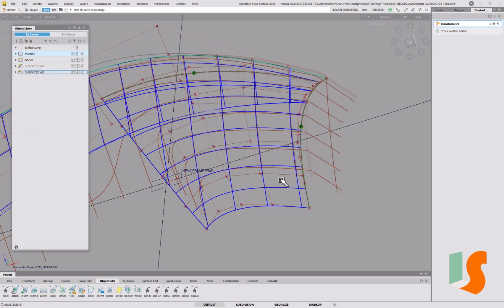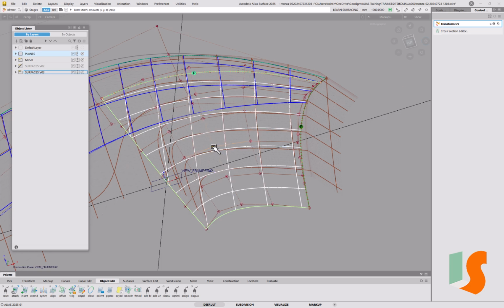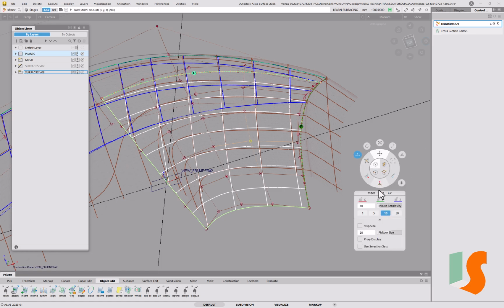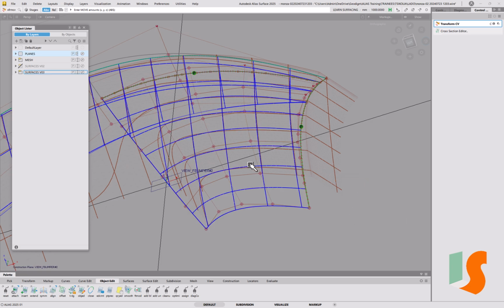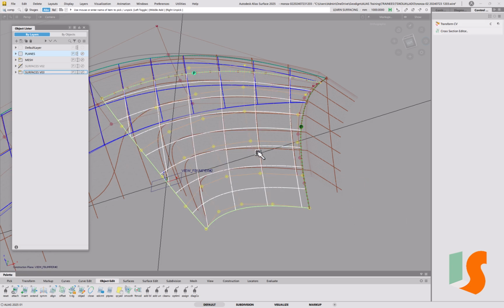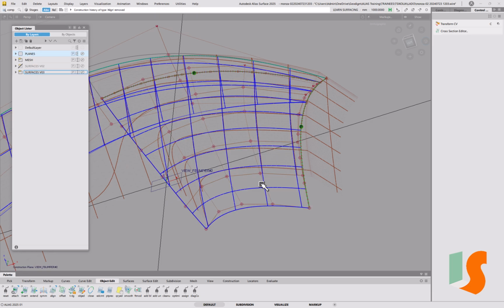I'd just like to flatten that out a little bit. I just feel it's a bit too curved. So we've got XYZ on and single CVs. So it's going to be maybe moving that point in. Put 1 on. Now I'm wondering, of course we've got history on, haven't we? Because I've got history on, I was thinking, why is that CV not moving? It's because we've got history on, because I put blend on. So that means all of these CVs are affected, and therefore nothing's going to move. So I've got to delete the construction history and then move from this point.